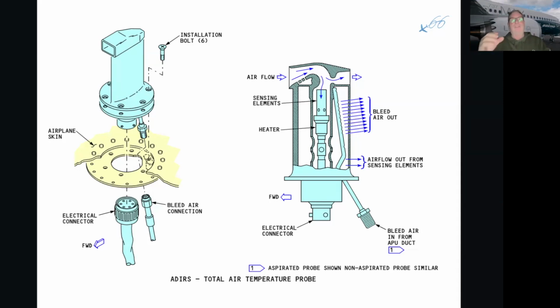All right, and it's just a reaffirmation. We can't just rely on any old data, because the formula we've got to calculate the temperature as we increase in altitude is used for a standard atmospheric day, at 1013 millibars. And it's not a very common phenomenon, 1013 millibars.